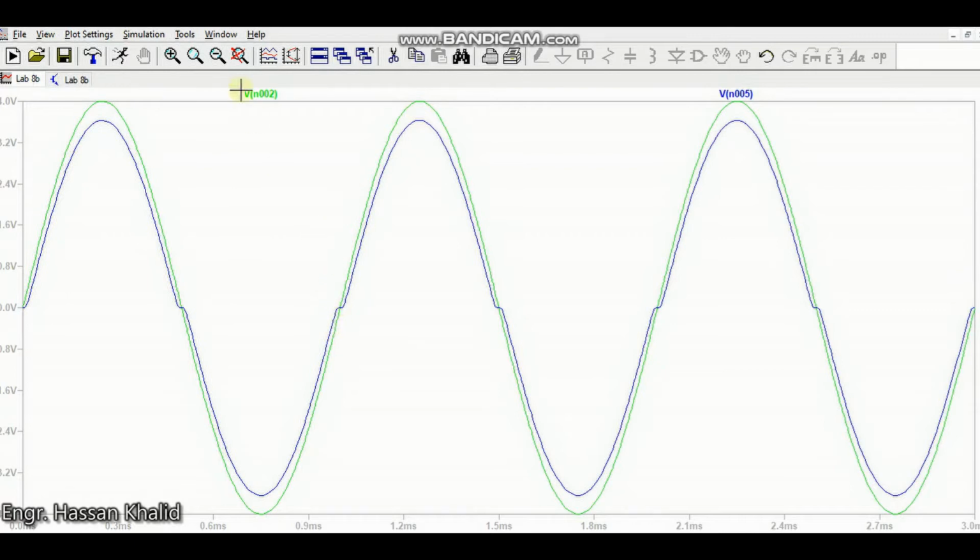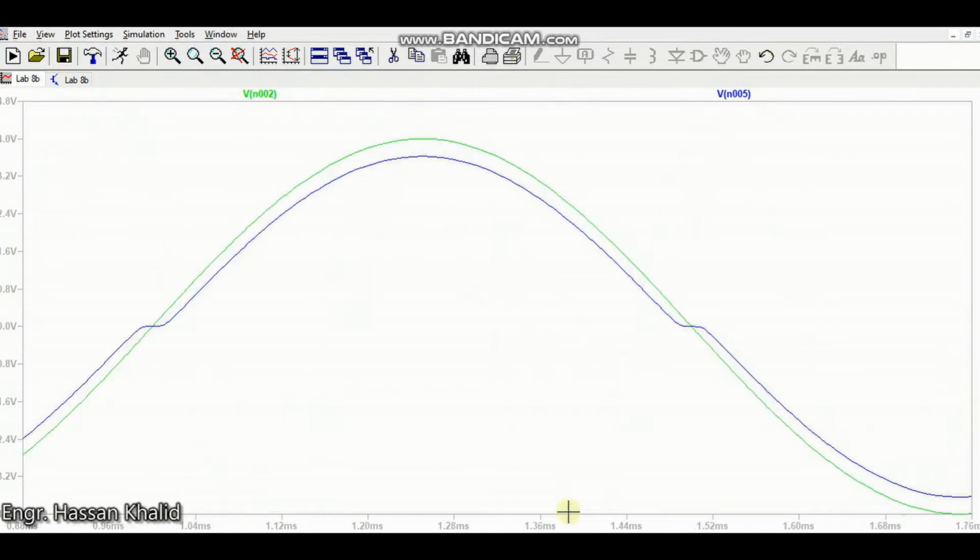You might observe two differences, one in the amplitude and the other one in the biasing, you can say. Now the blue waveform is actually saying that the base to emitter junction is not going into the conduction state at once. This means that the voltage at the base to emitter junction is not sufficient to cause the diode to get into the forward conduction region at once.